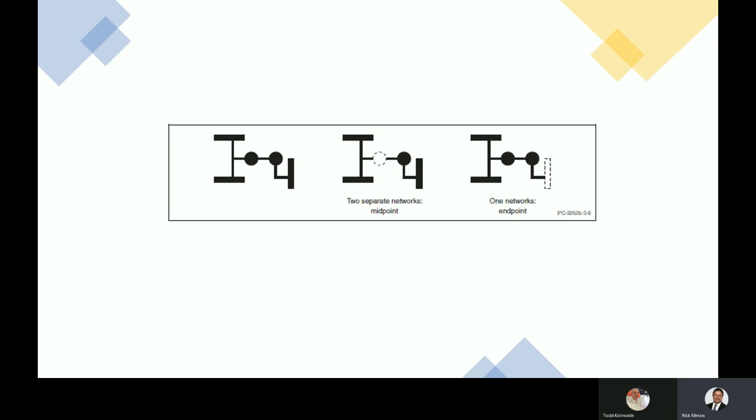So in some of these classifications there are test levels, as Todd mentioned, test level A, for example, where we would remove some of the points in the middle of the net, and they would be more of a straight-through point. If you had a line across your PCB with a point A on the left edge, point C on the right edge, and point B in the middle, current can flow from A to C without any interference from point B in the middle. Current can flow from A to B. Current can flow from B to C.